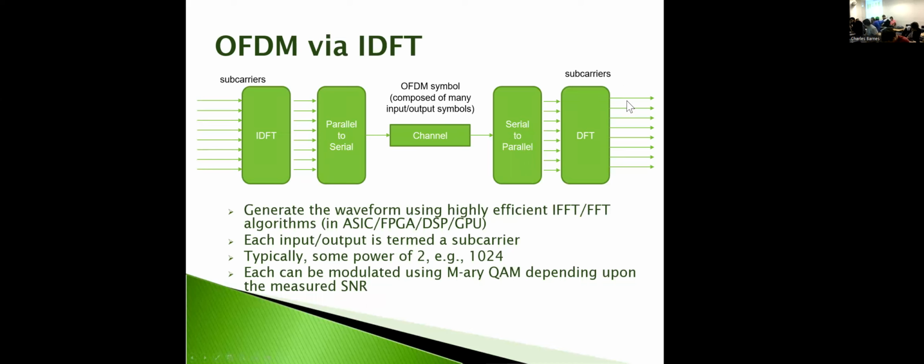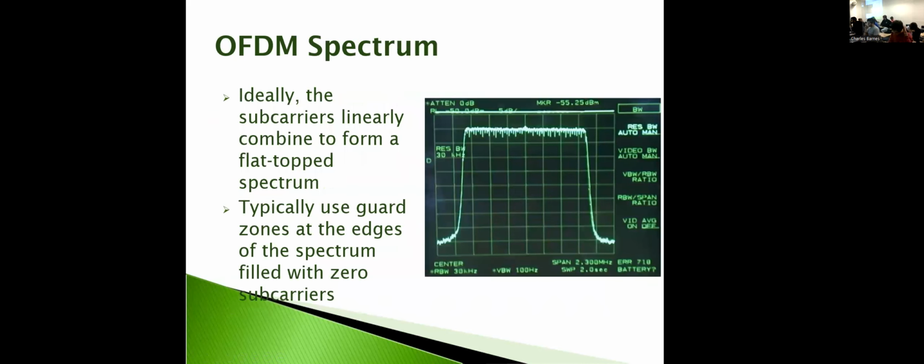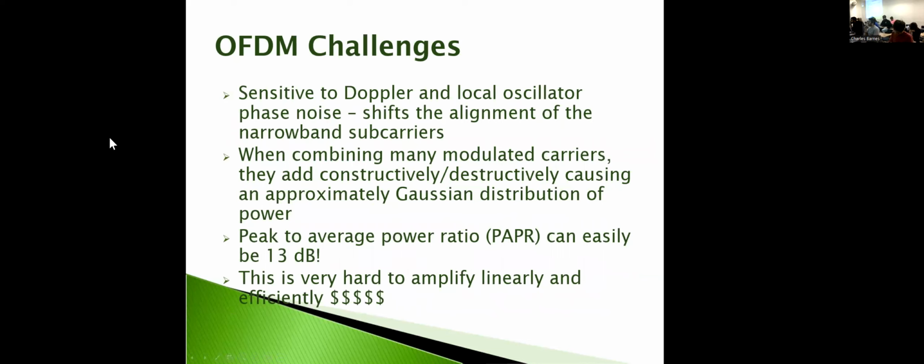So I've got to figure out how to compensate for that, or I'm going to have part of the signal that was supposed to be in subcarrier one bleeding into subcarrier two, and on down the way, and that's going to make it really hard to separate out those signals. We basically lose our orthogonality when that happens.